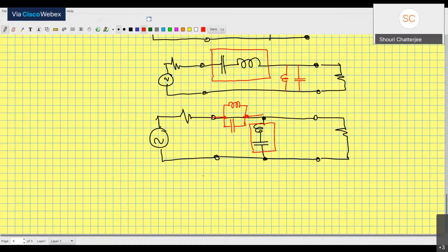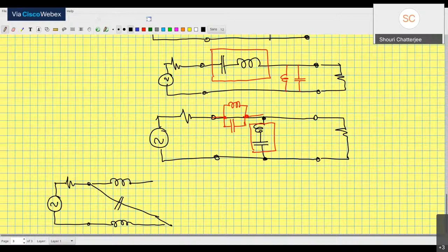All right, and then finally, the all pass filter. I don't know if you have ever heard of the all pass filter. So this is a filter that is used only for phase correction, not for frequency, right? It passes all frequencies. So the typical structure of an all pass filter is called a lattice. So this is how it's going to look.